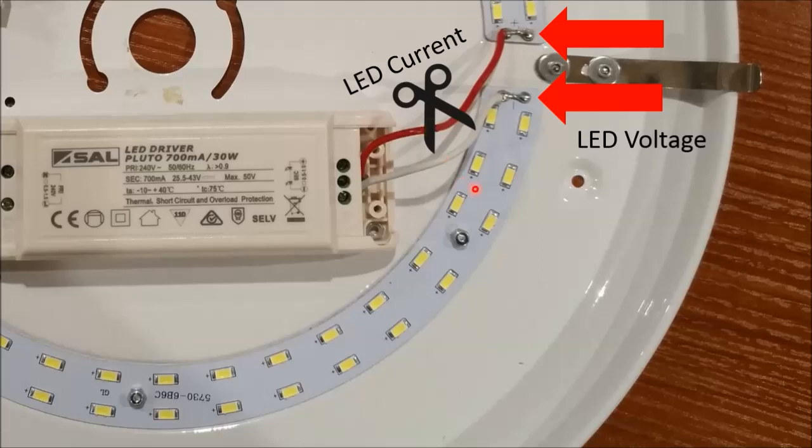You will need to have a 0 to 10 volt dimmable driver with a voltage range that covers your LED voltage, and the current that is equal or less than the current what you measured. If you take slightly less current, you will have a bit less light. For instance, 700 milliamp measured here, you can use a 600 milliamp driver, but it will be not as bright as previously.